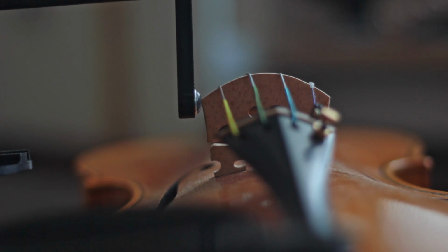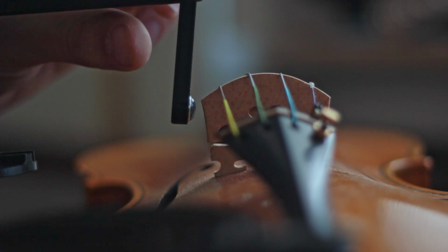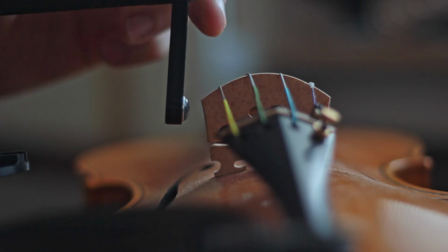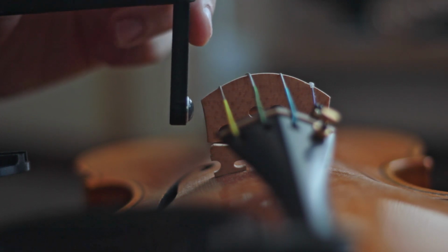The hammer should hang vertically when in contact with the bridge. Test out the excitation beforehand. Oftentimes you will be able to hear if it makes solid, short impacts. Here are some examples for you to listen to.